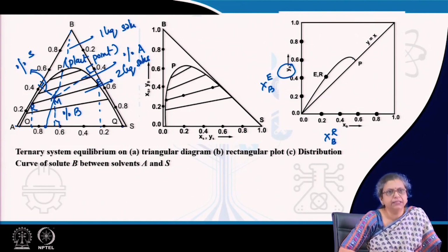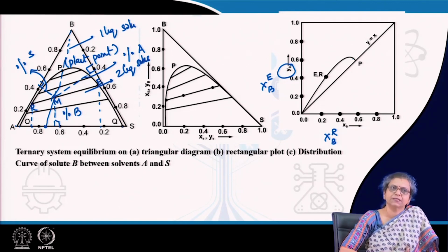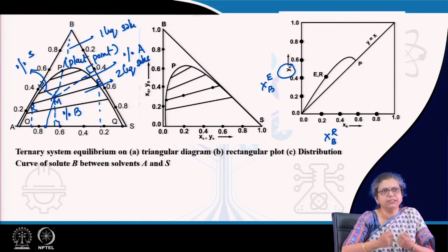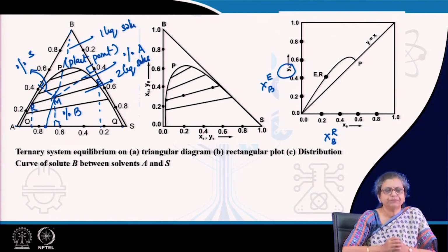Based on that we can express the equilibrium data either in terms of plots or in terms of K. The K values are usually used for ideal solutions, and they are very frequently used in hydrocarbon industries, because mostly those solutions are hydrocarbons, which form members of a homologous series. So, they form ideal solutions. Very frequently they are expressed in terms of alpha, which gives you the relative ease of separation.